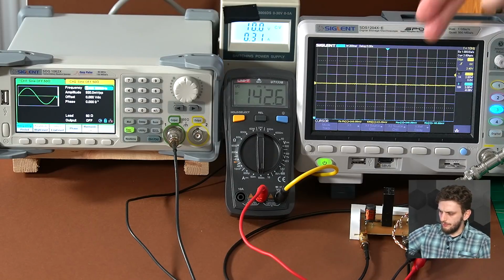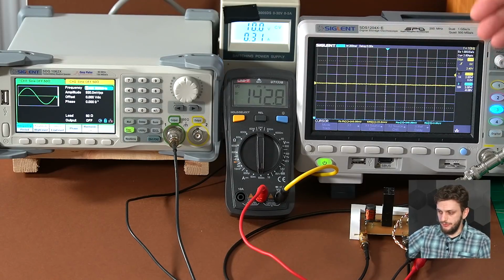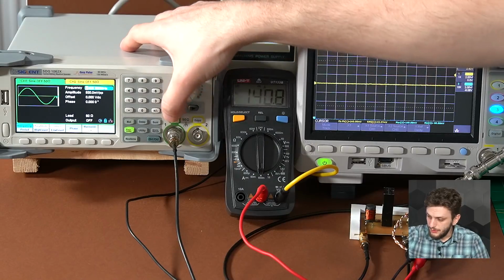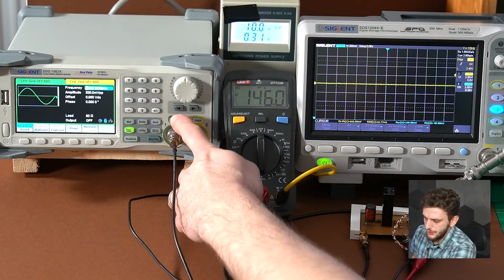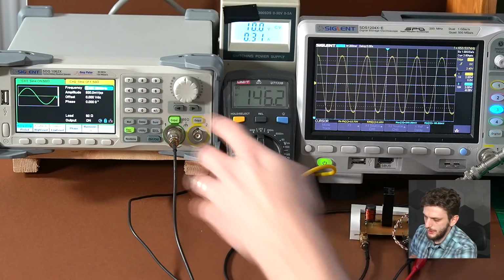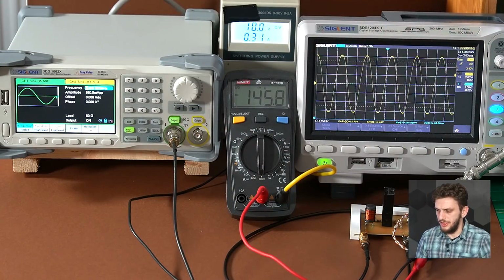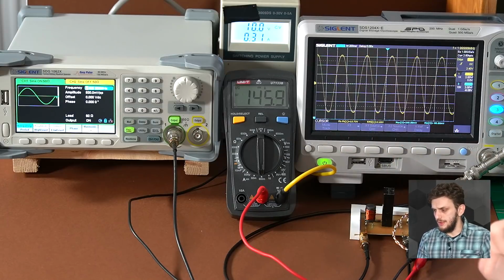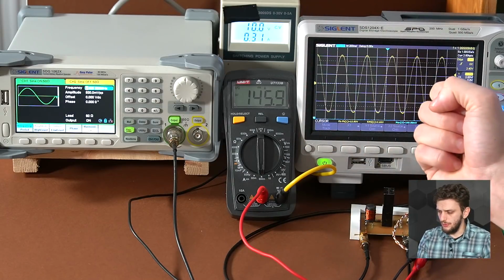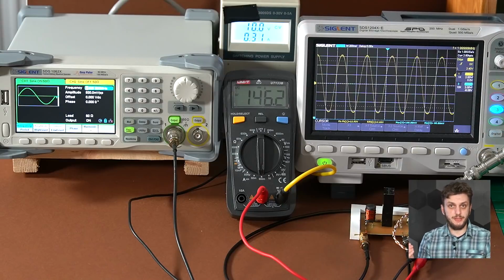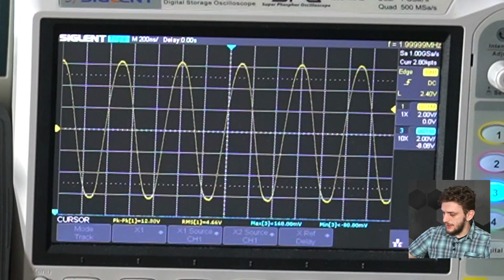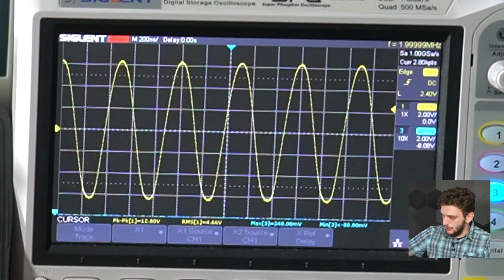Now at the moment, there is no output signal, we can see it's flat, and if we turn on the signal generator, we're at 446 milliamps with an output signal, not much has really changed. We are still in the same region, we see that current is slowly decreasing. Again, as some of the power gets delivered, the transistor is getting slightly colder, so we have a small shift in the current consumption.